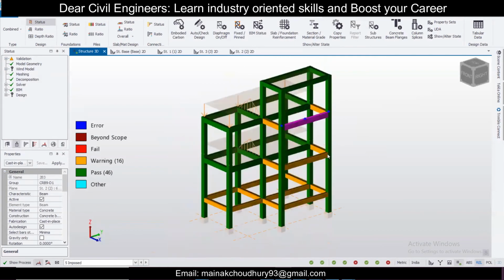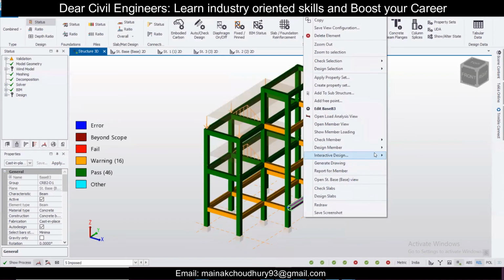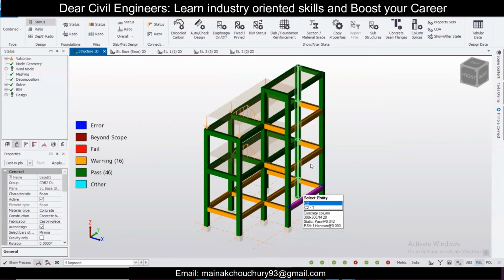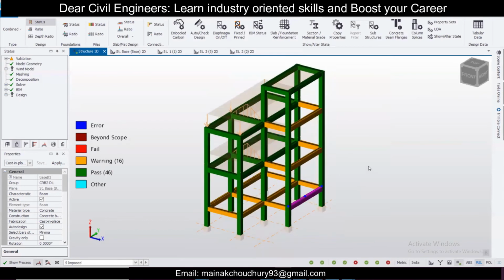Here they're issuing an issue for the axial force. Let's see the warning for the plane beam. I'll tell you that there is always a warning here if you're designing by Indian code, but it can be ignored here for the axial force. If you increase the moment or increase the load in this particular portion, then this warning automatically goes away. I'll just show you what I'm trying to tell.